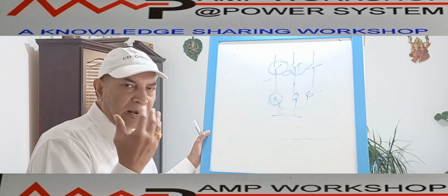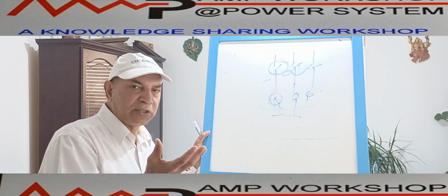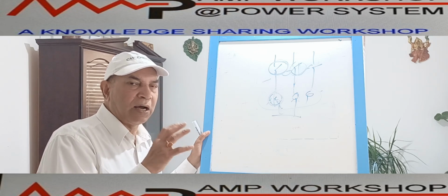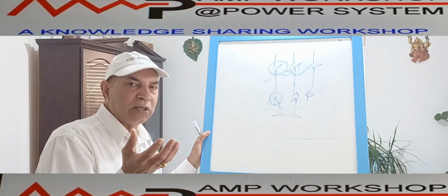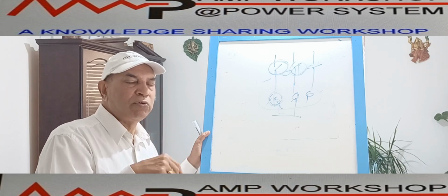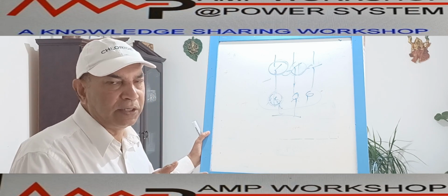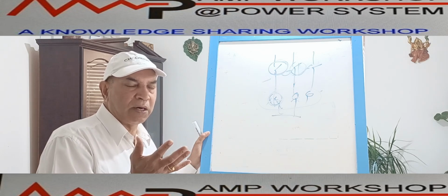In the case of an alarm circuit, you can use it in the same way on the PCB, or you can use a ballast resistor. But if you use a ballast resistor, then for protecting the LEDs from reverse bias or external high voltage stress or suppressed current, you have to use an anti-bias or reverse bias diode in parallel to the LEDs. So that is in brief, and then depending on the requirement you can design it.